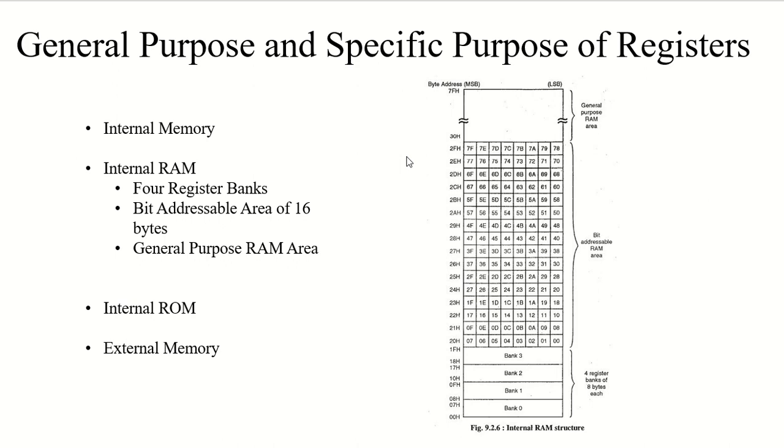So anytime you want to remember a binary event in your program, always remember to use the bit addressable RAM area. And if you don't know what binary events are, simple open switch and close switch operations are binary events, like 0 and 1 events. So a simple open switch and a simple close switch are binary events.